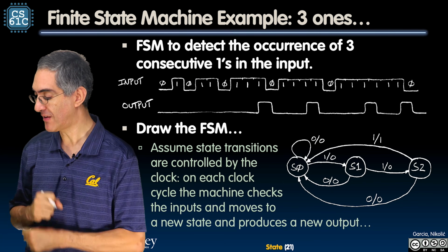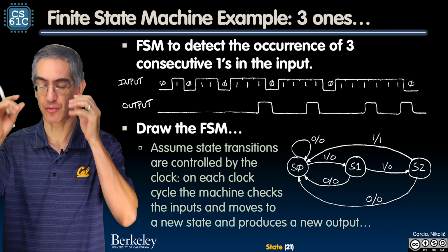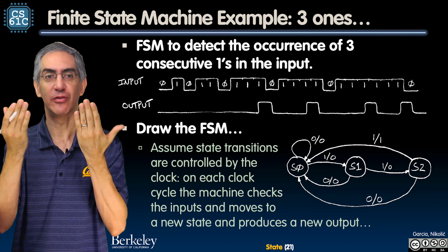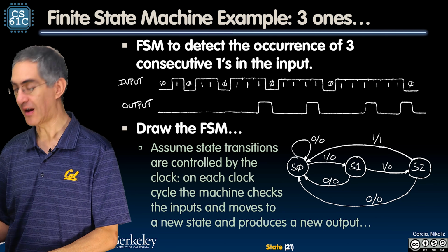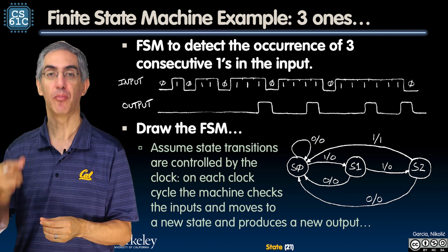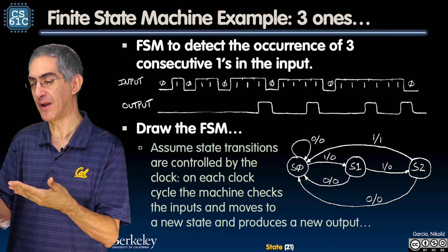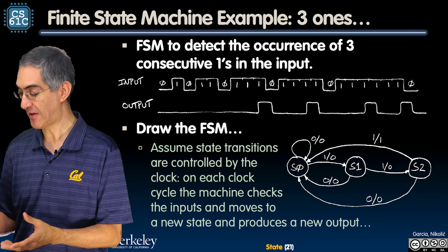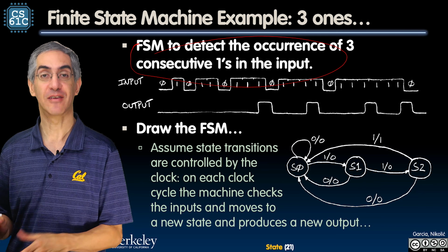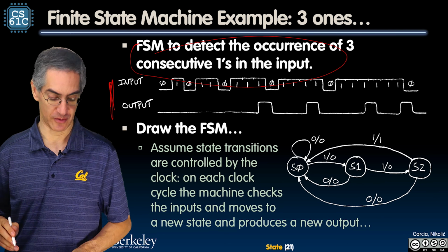So we're going to play with this on a finite state machine to detect 3 1s. Detectors are really easy to do. We've used those in exams before. It's a nice example. So what it says is when I have 3 1s, I want to output a 1. And then should I continue to output a 1 when I get the 4th one? No. This has to be part of the spec, by the way. You need to tell me what happens on the 4th one. And then usually this input-output example tells you what to do on the 4th one.